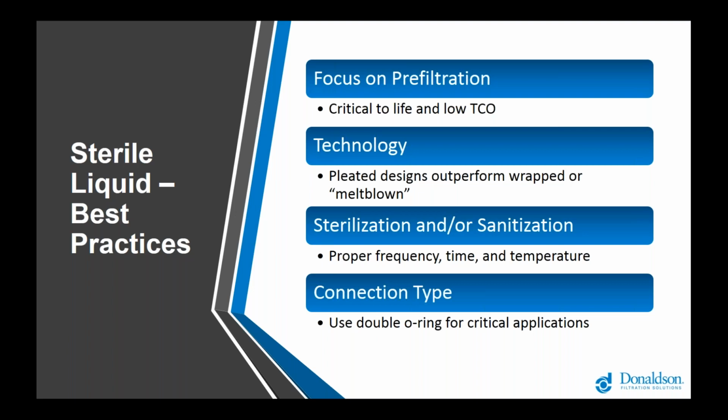Similar to compressed air applications, the systems and the filter elements need to be sterilized or sanitized with hot water on a regular basis. This will, of course, avoid microorganisms forming the very difficult to remove established colonies that can form if they're left long enough in a hospitable environment to be able to thrive.